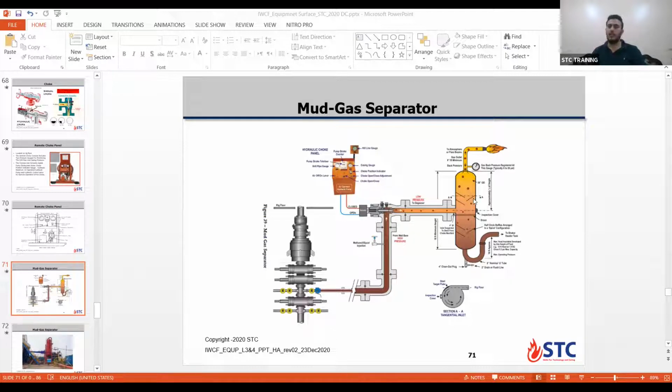We need always to keep the operating pressure high. If the operating pressure is low, this means that the liquid seal hydrostatic pressure has decreased due to some gases or some condensate having entered the well.